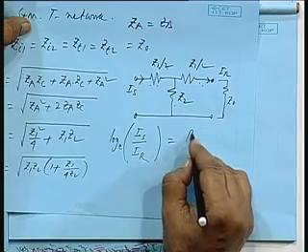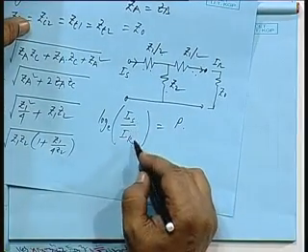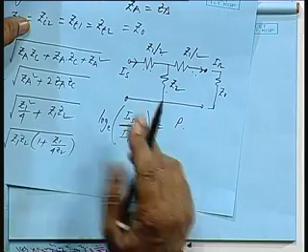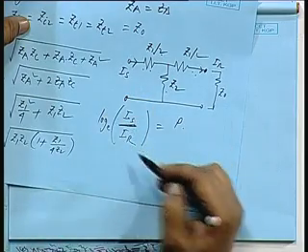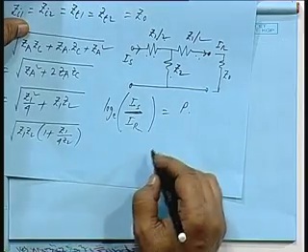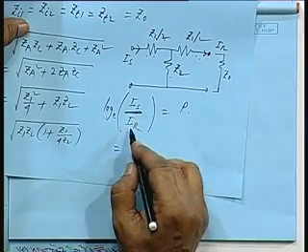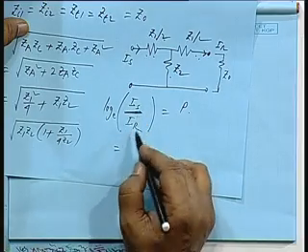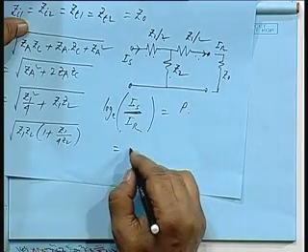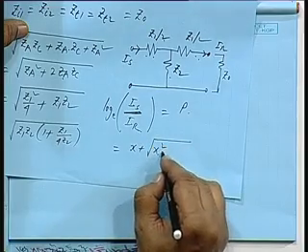This was defined as a quantity p, which is basically representing the ratio by which the current falls in a logarithmic scale, and that was shown to be log of I s by I r to the base e, and this was x plus root over of x squared minus 1.